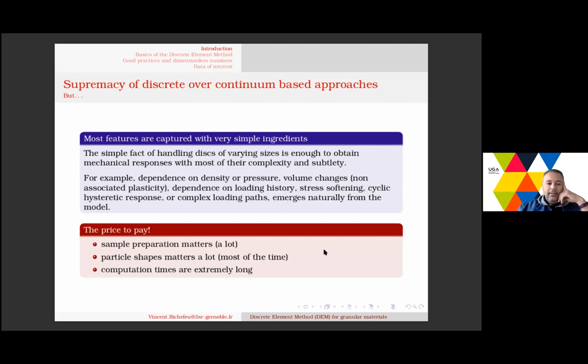One is the fact that the initial state of your packing is of great importance, and the sample preparation matters a lot, actually. So you can make mistakes if you do not take care about the sample preparation, and also it's long, and the particle shapes also matter a lot.